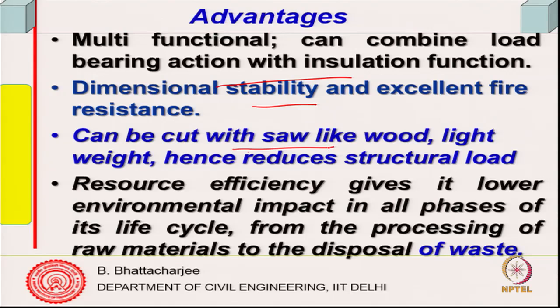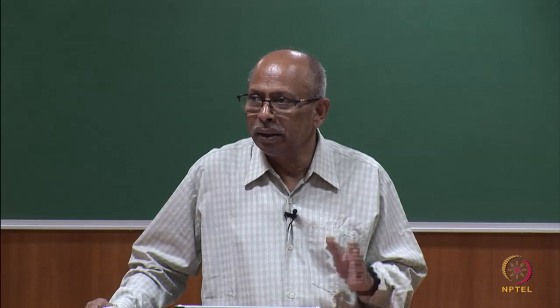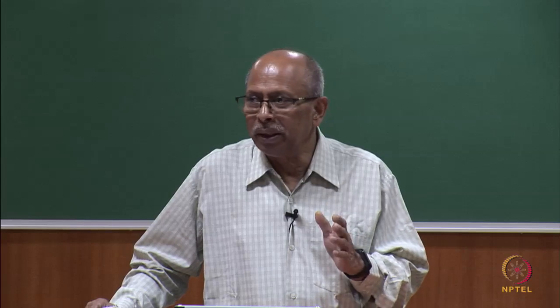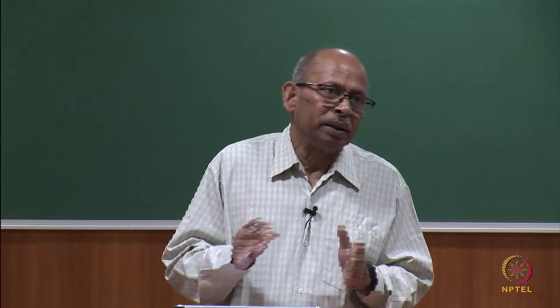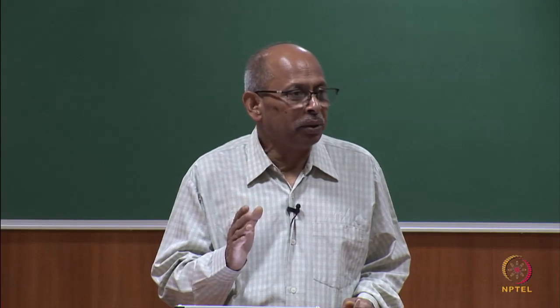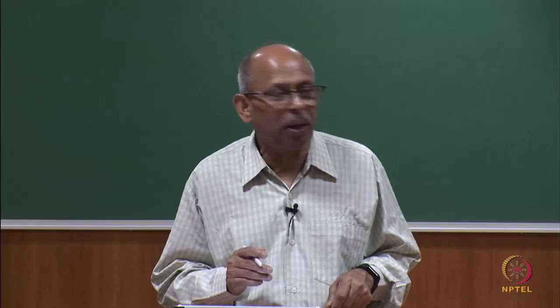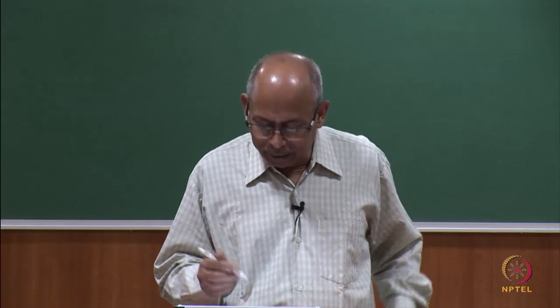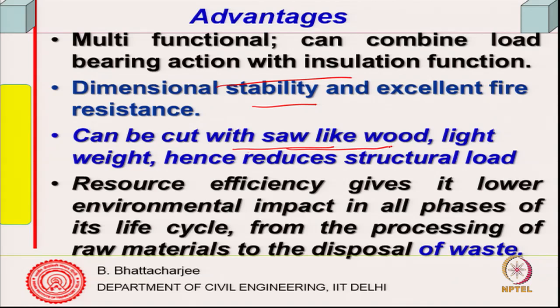So, it all started with basically they were trying to get a replacement for wood. AAC, replacement of wood long back, not today, 1925, trying to replace wood with a cementitious sort of material which should be cut, which one can cut into shape. So, that is how it originally developed, added the chemical, and therefore, it can be easily saw cut like wood, lightweight, and hence reduces the structural load.